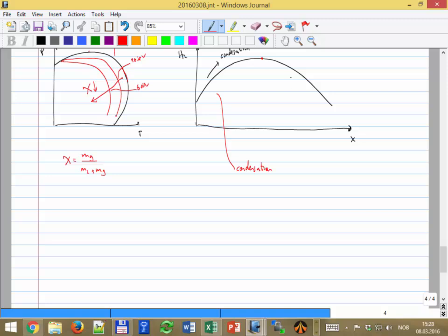And here, one explanation that was given is evaporation. Okay, but you are missing something. How else could the holdup be changing? Just because of the dynamics of the multiphase flow, right? Just because the liquid begins to go slower than the gas.